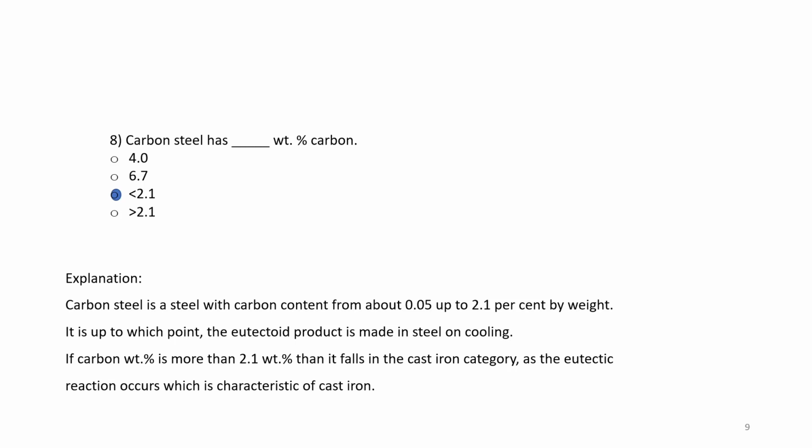Steel scrap already has carbon percentage in it. And if you are using pig iron, then its carbon percent is as high as 4 weight percent. So you need to reduce the carbon percentage, not add carbon. For that you add oxygen to it. Oxygen will take care of carbon and it will form CO2.